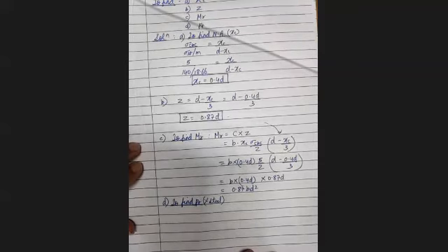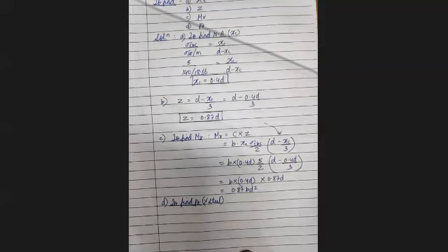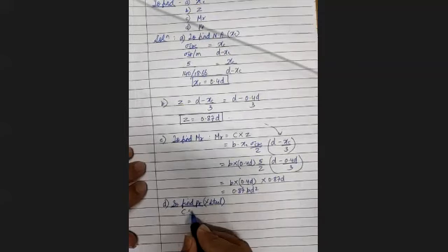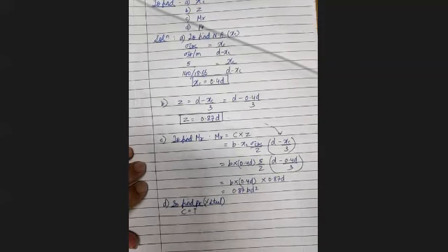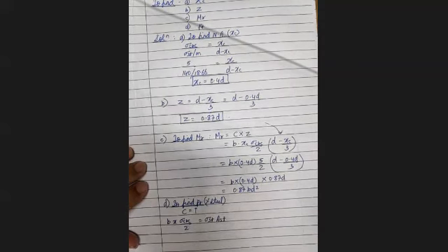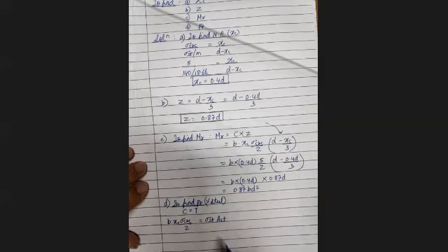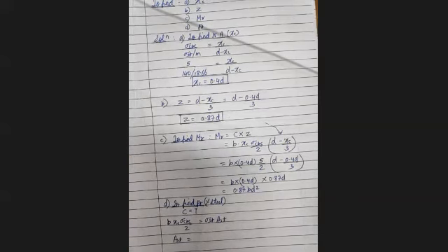So now for this, we are going to make use of the second formula. That is, we will equate C equal to T. If you have remembered, so by equating C equal to T, we get B into X into sigma CBC by 2 is equal to sigma ST into AST. Is that fine? So now substitute the values and find out AST. Anyone find out the value of AST?